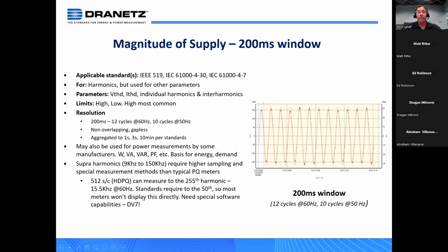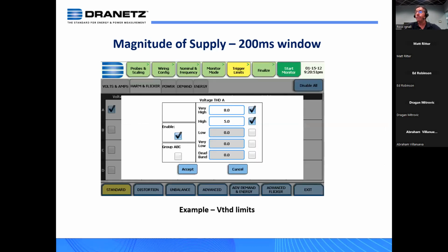But the harmonic and time plot calculator of Dran-View, a standard capability of Dran-View 7 Enterprise, can do that for you. An example of doing that is the G55 standard in the UK, which required going up to the 100th harmonic. They doubled it in the newer G55 standard that they released over the last few years. So the solution for our customers was to use Dran-View 7 Enterprise to pull that information that their meters already had, that they've been using for years.